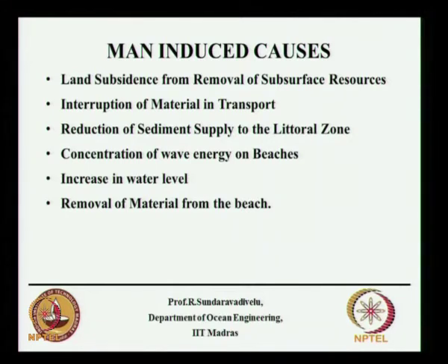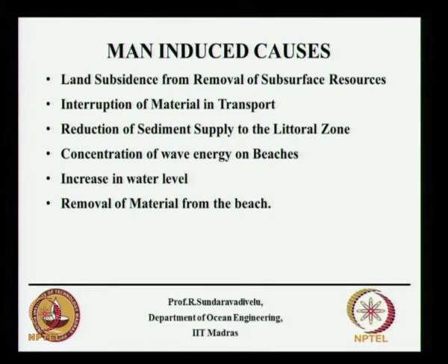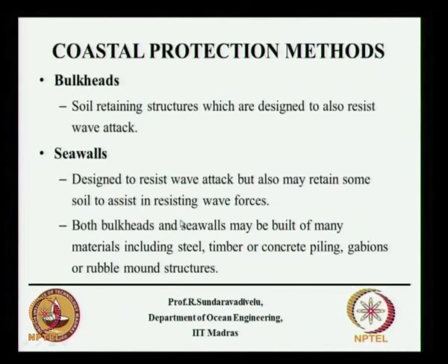So when there is an interruption of transport, on one side it gets deposited, that means whatever sediment it was carrying in the littoral zone is depleted on the northern side, so that causes erosion. There is a certain concentration of wave energy on the beaches; if there is a concentration of energy, the erosion is more. The increase in water level is also a man-induced cause because of the temperature increase, global warming and things like that. So we cannot say the increase in water level is natural, it is also man-induced. Then removal of material from the beach, that is the dredged material.